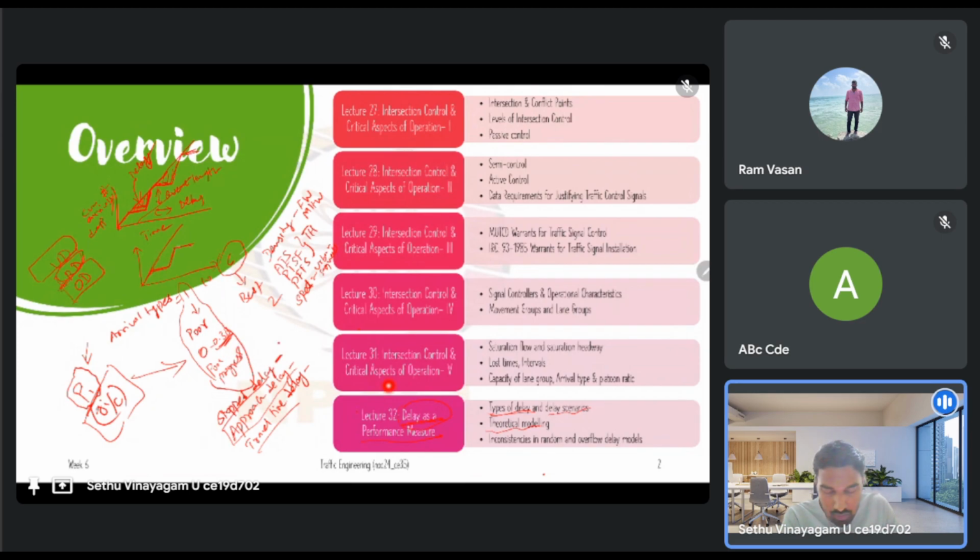Because of lower capacity, the queue keeps growing, and then again there will be clearance, and it keeps growing, and like this. So in this case, the departure curve is not catching up with the arrival curve, so this area is going to keep on growing, right? So there will be a divergence between the arrival and the departure curve.